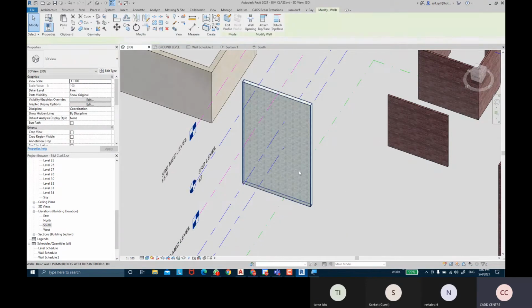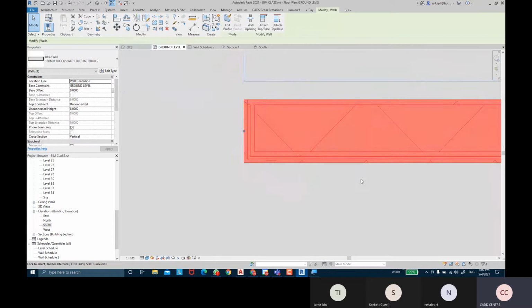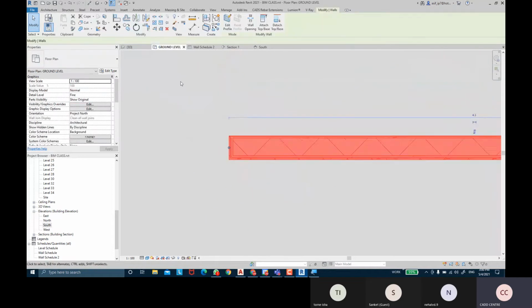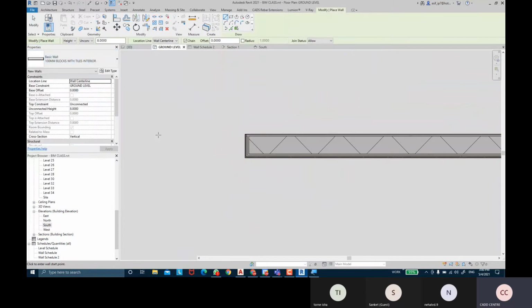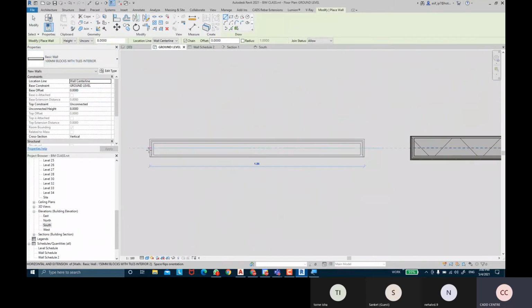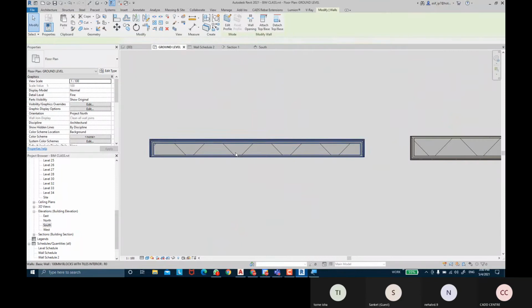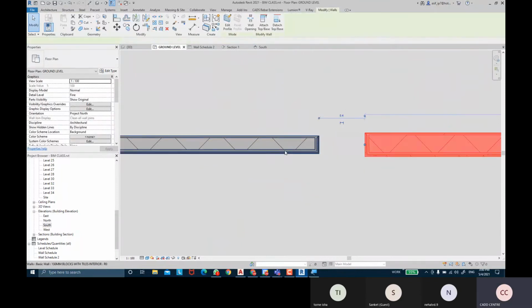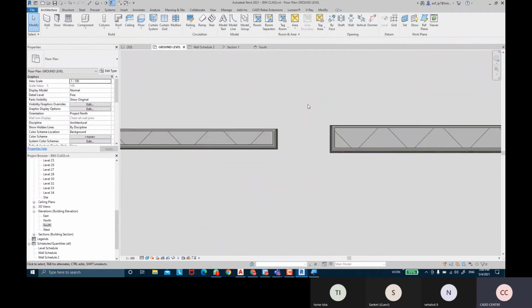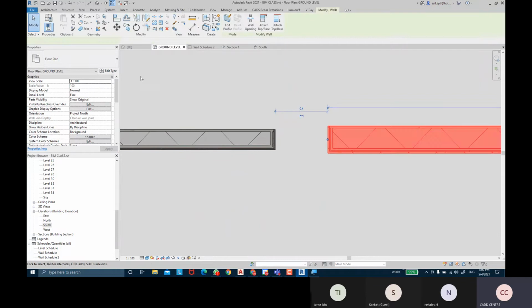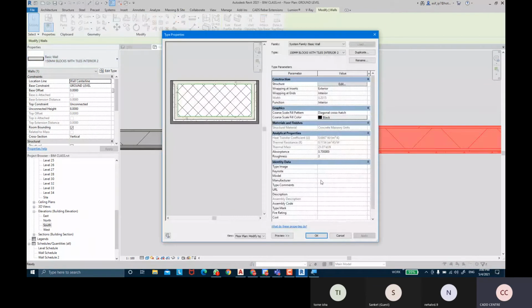So I have two similar kinds of wall with similar properties, but only the core thickness varies. One can be of 100 and one can be of 150. Both the properties are same, only the thickness varies now. So if you have created one and applied the entire properties, you can duplicate it and keep it for the next type of wall also.